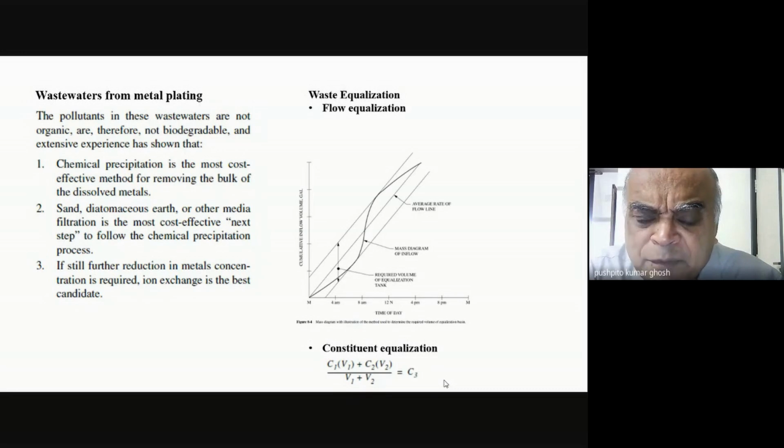Unless you have a continuous plant, where of course the same thing will happen every hour, but if you've got batch processes, and different types of batches being run in the same factory, then you may not actually get a constant volume or concentrations of the different constituents in your effluent. Then the question is, how exactly will I design my effluent treatment plant?